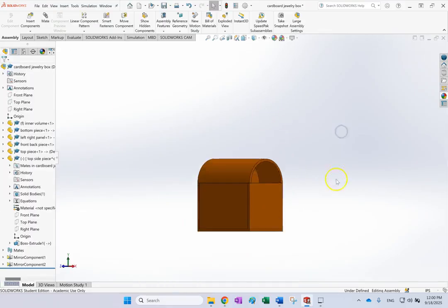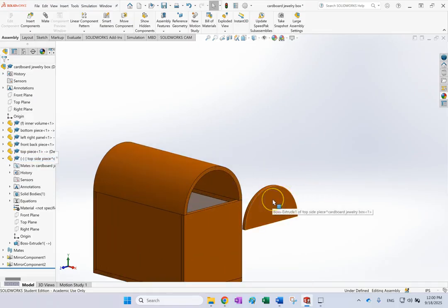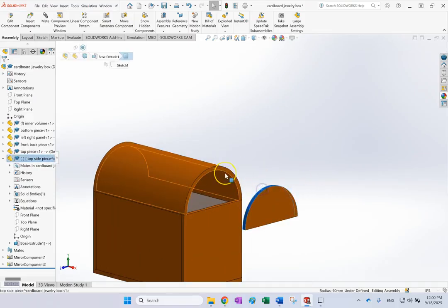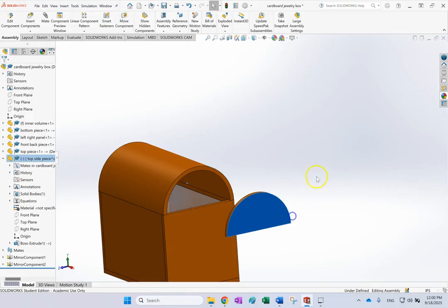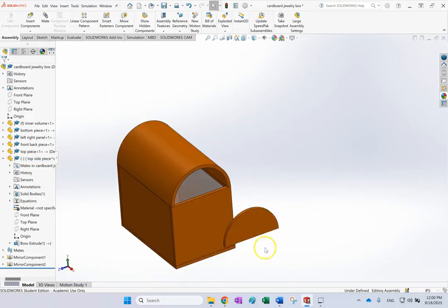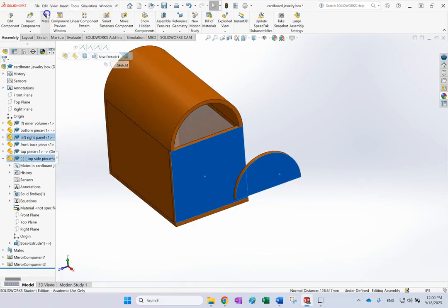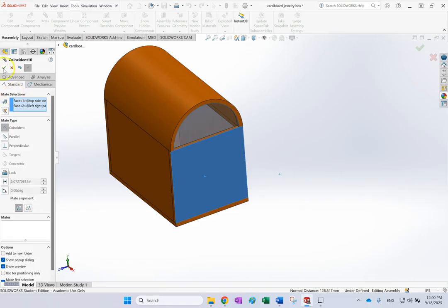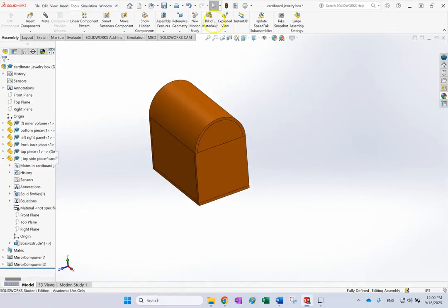So now if you look at them, this part, if you try to spin it, it is not going to work. But if you didn't do that lock, this arc and that arc would stay concentric, but you can swing this basically like a pendulum. But right now, because you locked the angle and you initially started this horizontal, that is like a perfect angle. And now all I need is to force these two to be coincident. And that should make it fully defined. Look here, fully defined, done.